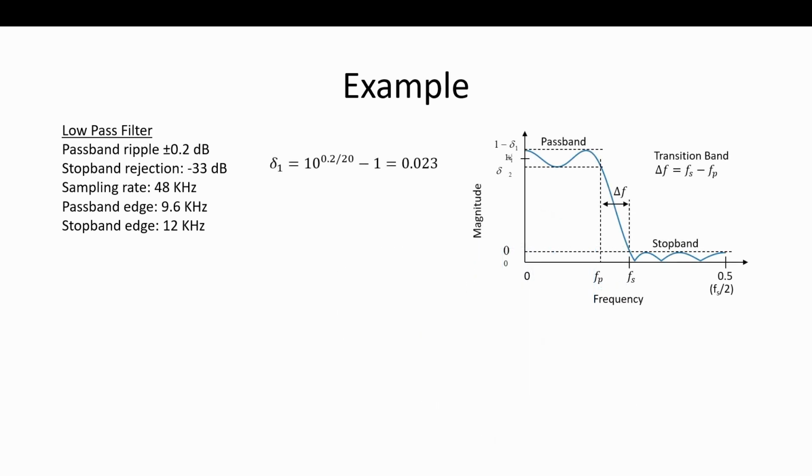and you'll see here how that estimator worked. So the passband ripple, what you're doing, you're converting dB back to a magnitude quantity. So it's dB as a magnitude, ratio of magnitudes, it's 20 log of that ratio. Because dB as a ratio of power is 10 log of that ratio. So if you have the value 0.2 dB, you want to convert it back from dB, we're going to divide it by 20 and then the antilog and subtract 1 because it was 1 minus that, and that's 0.023. So that's the example of delta 1.